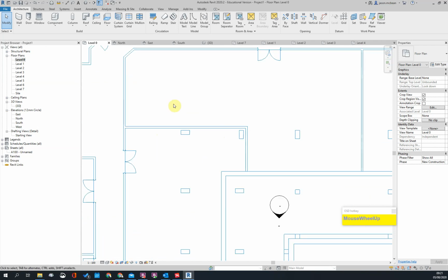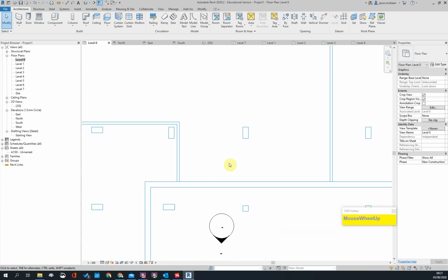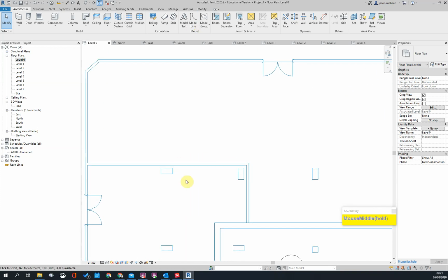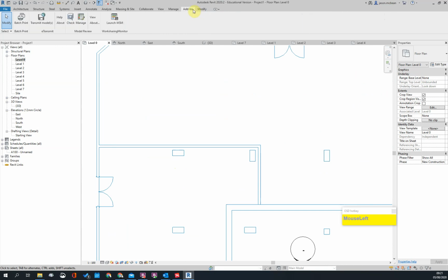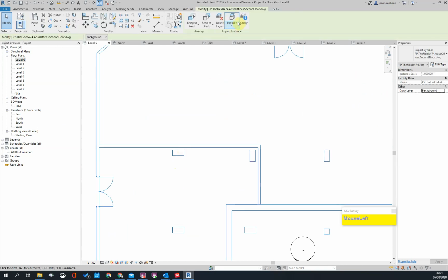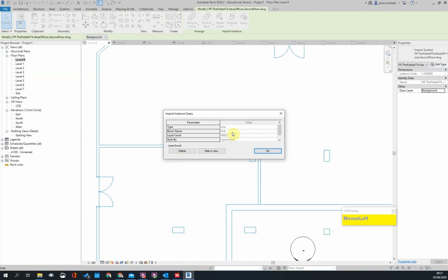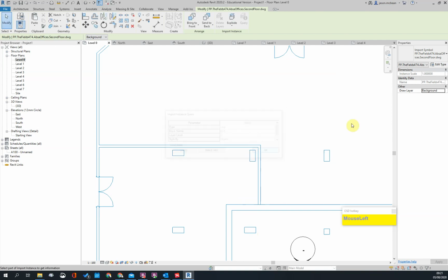You can see these are structural columns, for example, and we'll need to start working those up. The best way to do it, if the AutoCAD file has been done well, is to collect the AutoCAD file and use the query tool. That's not a good layer, so they've used terrible layers. Let's see, no, they've got layer C, so maybe that will work.